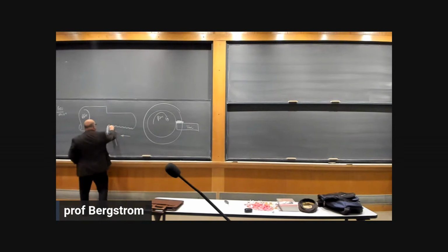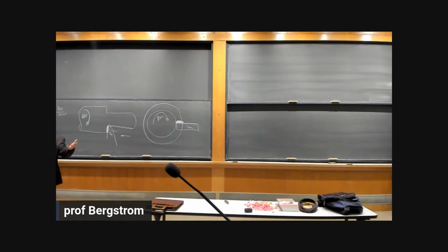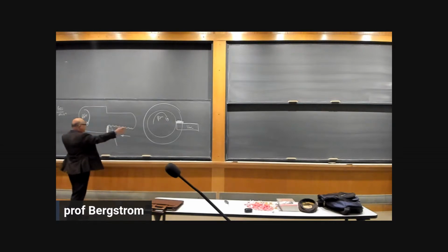This top surface of the tool, that the chip slides along, is the rake face of the tool. So this line here represents the rake face. Does that make sense? This geometry gets a little confusing sometimes. So we've got this stuff moving along. Now, this distance between the little bumps, what does that equal?